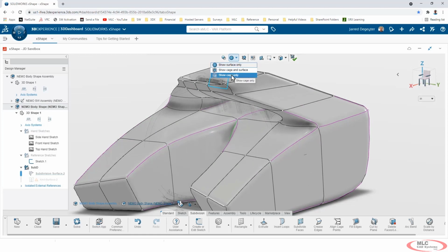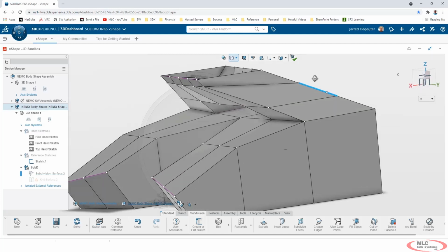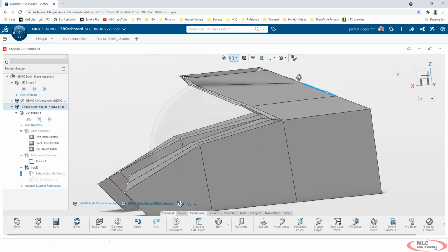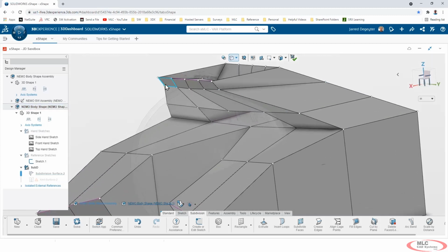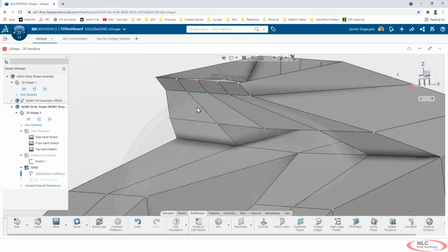Now, similar to working with a style spline, we have the ability to turn something on that shows the underlying cage that's driving the surfaces that we have. And this allows us to very easily see anything that might be out of alignment. For instance, these bottom vertices here, I can align them up by just making a pick in succession. I can pick those two outer areas and then make the internal picks here. And what I can do is align vertices to each other. And this just snaps them into one lined up little area for me. So this makes it look really nice.